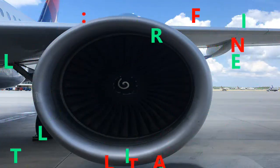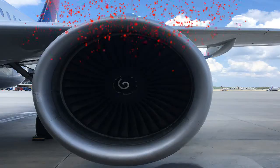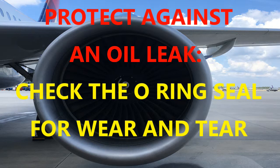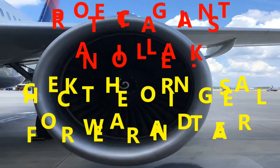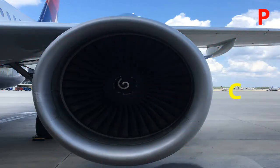The other thing you want to be aware of, just from a visual inspection, is to make sure that the O-ring seal is not worn, because it's called a seal for a reason. You don't want to have a leak from that point, and on that cap, you want to make sure that the O-ring seal is not cracked or broken, whatever. Okay.